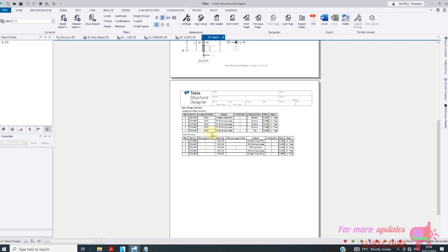Never use H12 for column. I'd rather go for H16 or T16. Never use T12 for column, especially for that kind of building, which is, you can see, G+5. The minimum you can do is 16. Don't go with this size of column.